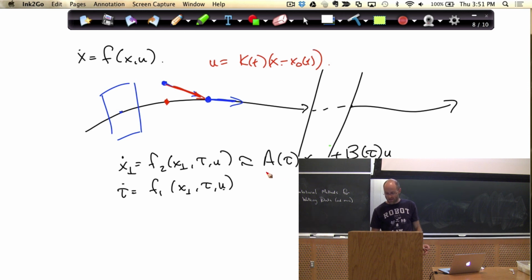It turns out stabilizing the transverse coordinates is the right way to make yourself safe under this projection, so that you can search for the closest time in the trajectory and execute a controller that tries to drive this error to 0. So if you stabilize the n-1 dimensional system, then what you're really stabilizing is the error dynamics in the projection to the closest point on your trajectory. Does that difference make sense?